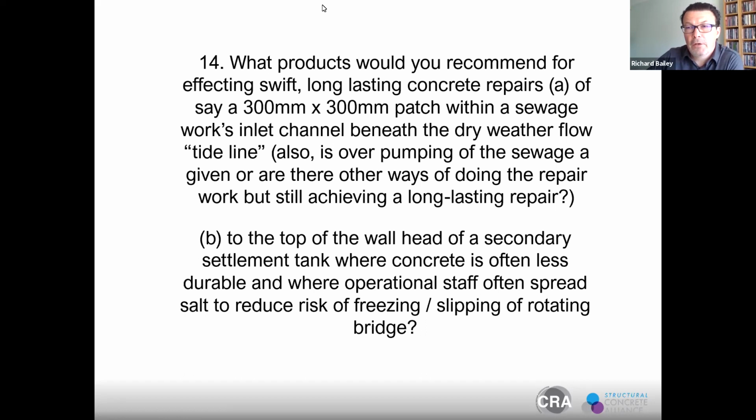The load applied on the aris edge of a concrete joint from a hard, small wheeled piece of kit like a forklift truck is quite considerable. Those impact forces can damage the aris repairs, but if you've got voids underneath, you can also get minor deflections in the slab. So let's look to stabilize the area around the joint.